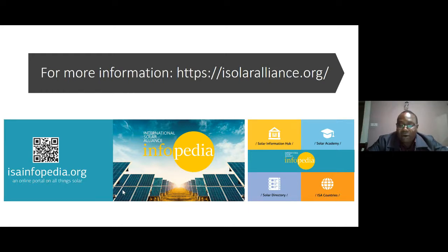I'll say yes, and of course, the engineer who is working on your system will have to determine which is the best charge controller or inverter to be used. For instance, if it's a small system for home lighting and basic use, then for cost reasons you will just go for a PWM charge controller, maybe, or a shunt type charge controller, which is quite cheap and simple to get.